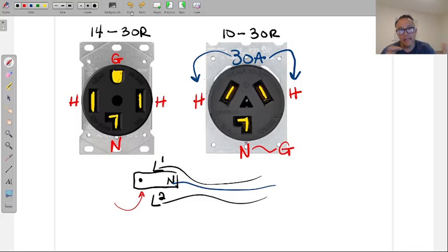We're allowed to change the plug on the dryer, not the receptacle in the wall, to a 3-wire situation. We get rid of the little ground that was here. We don't have a ground wire anymore. We do not bring our neutral to that one, because the neutral here is doing the coil thing. It's connected to the coils inside and all the things that are going to activate the dryer.